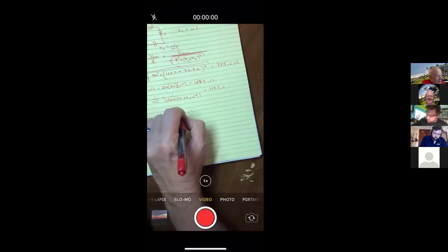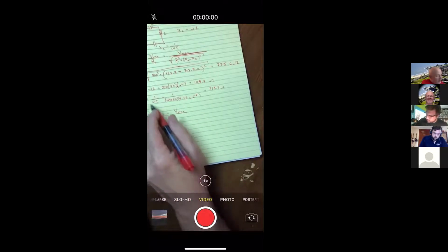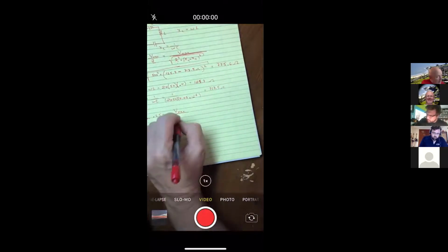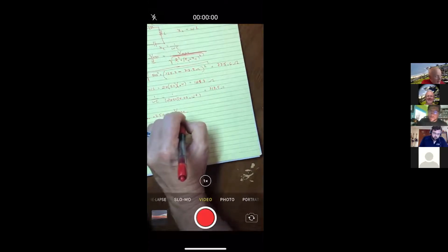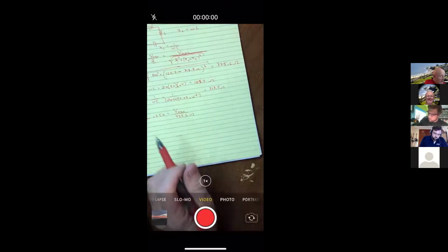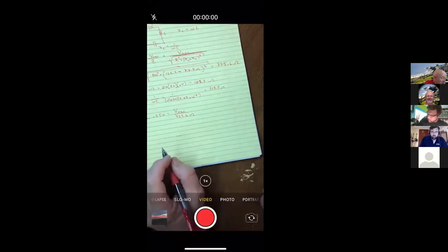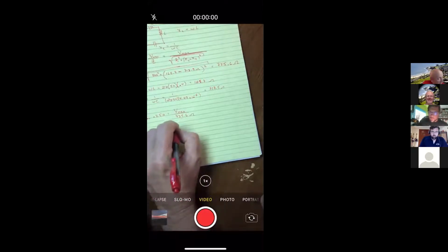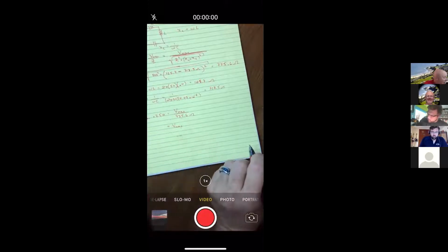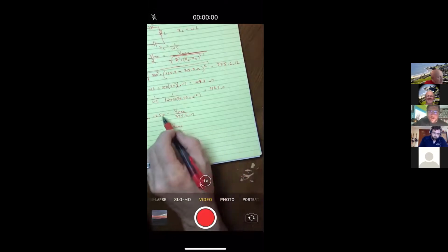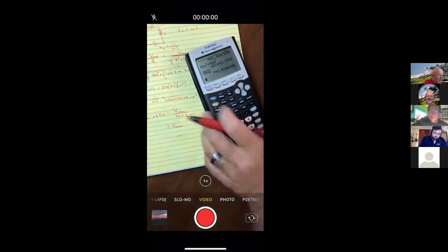And now that would correspond to a maximum voltage, and then I can divide it by an impedance of 775.6 ohms. So the three of these together, you might say, are the equivalent of a resistor of 775.6 ohms. Although probably shouldn't say it that way, because the inductor and capacitor act so differently in many other aspects. But in terms of opposing the currents, that's what they are equivalent to.